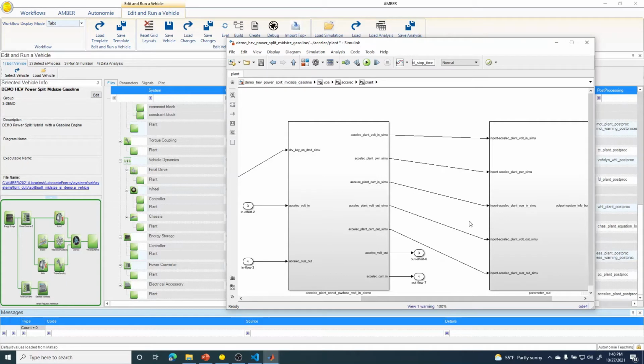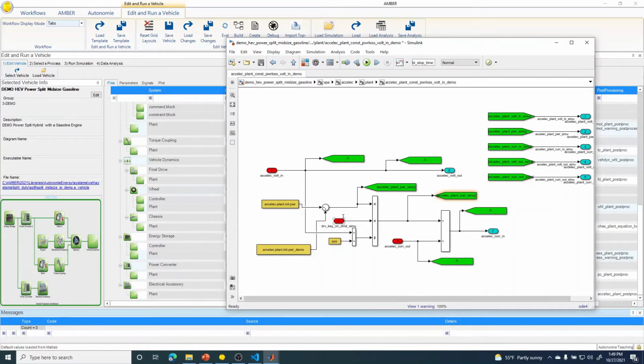You might ask, well, what defines the buses? What defines input buses and output buses? Those input and output buses are assigned to connections based on the configuration files. So it's the configuration files that kind of define the signal flow architecture of the model. And it's these lowest level terminating blocks that actually put signals onto those buses. So we'll go into this model, and you can see the parameter has been added here.